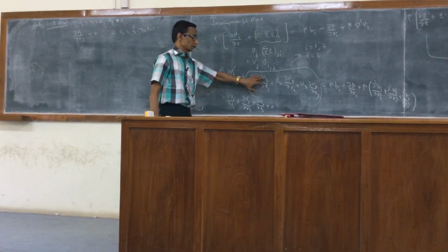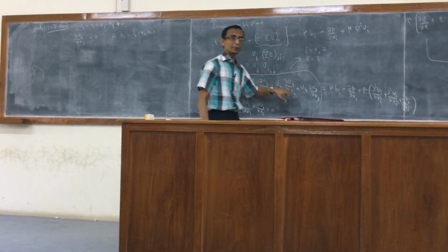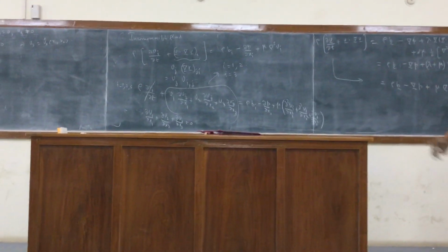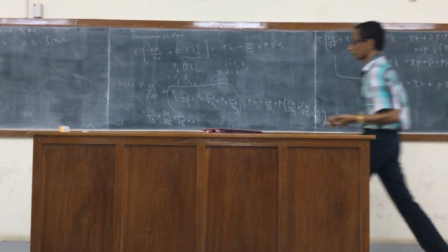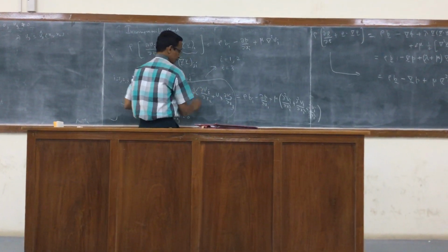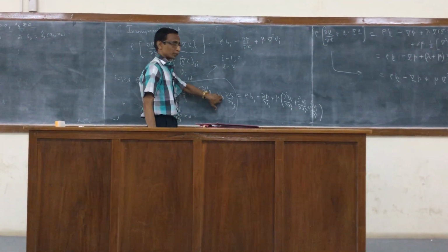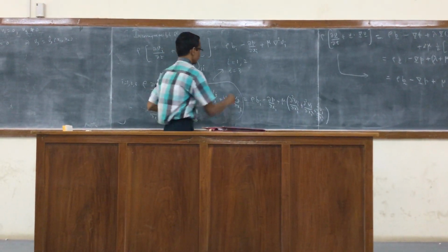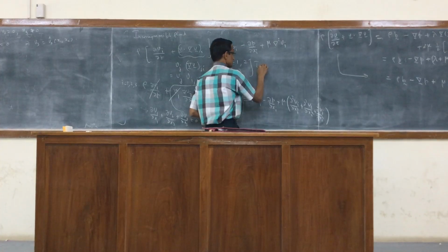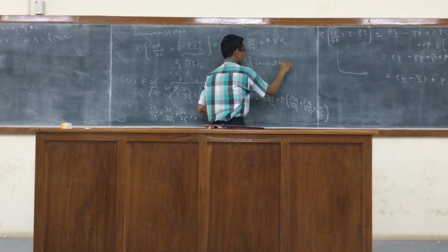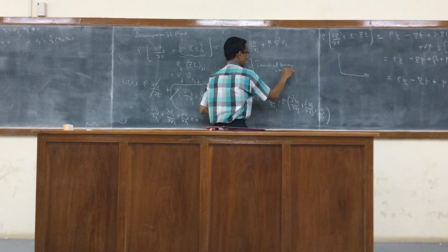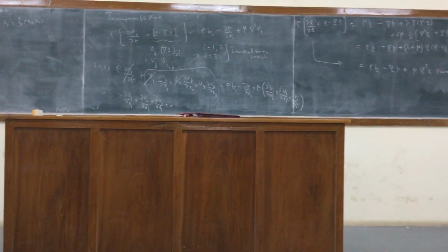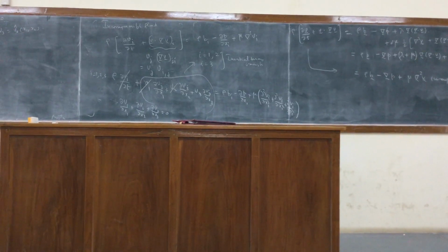So you see that dV3 by dx1 and dV3 by dx2, which need not be 0 in the general case, are multiplied by V1 and V2, which are 0. So this is 0, this is 0. V3 is of course non-zero, but the continuity equation says that dV3 by dx3 has to be 0. So for i equal to 3 also, the inertial terms vanish. So we get a considerable simplification of the equation of motion for so-called one-dimensional flow.